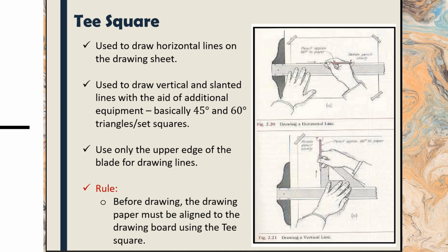Also, before drawing, the drawing paper must be aligned to the drawing board using the T square. This will be demonstrated for you in the next lecture, where we'll demonstrate how to align the drawing sheets properly on the drawing board with the aid of the T square.